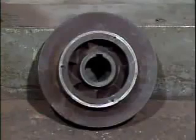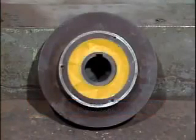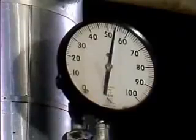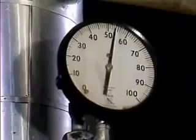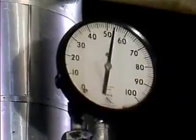Impellers can also be classified in other ways. For example, closed impellers can be further classified as single suction impellers or double suction impellers. This impeller is a single suction impeller. It has only one suction eye, so there's only one place that the liquid can enter the impeller. Single suction impellers are fine in applications where the pressure change across the pump is relatively low.